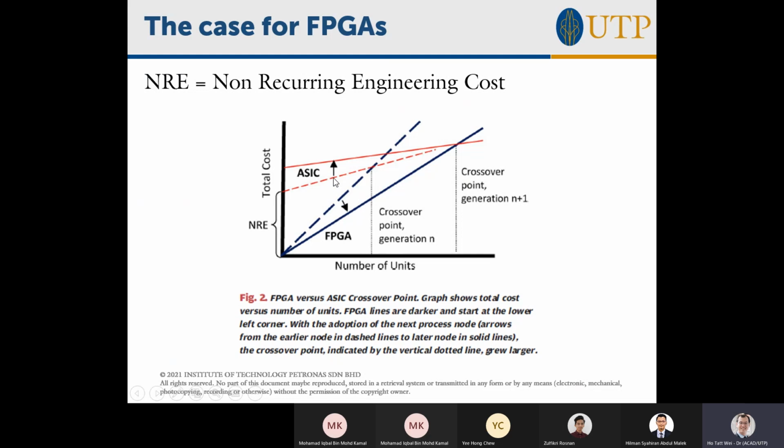And what we are seeing is that over time, as we implement with better and better fabrication technology, meaning the transistors are smaller, the cost for ASIC is going up: the non-recurring engineering cost, the overhead to even get started. Why? Because as you make smaller and smaller ASICs, the fab and the engineering work you need to achieve that is more, because the devices are less reliable and it's harder to get them to work, right?